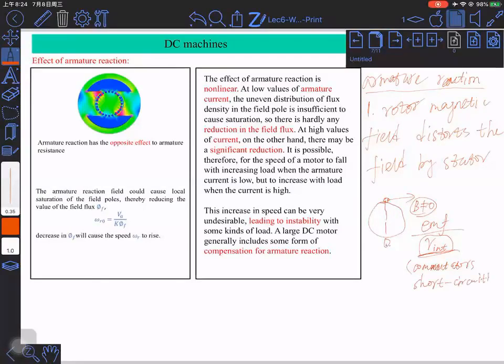For the external circuit, we don't need to worry too much because we have the external circuit's resistance there. But for the internal circuit, the resistance is very small. It's not 0, but it's approaching 0. So we have a huge current, and that current generates sparks, significantly shortening the life of the brushes and the commutators.